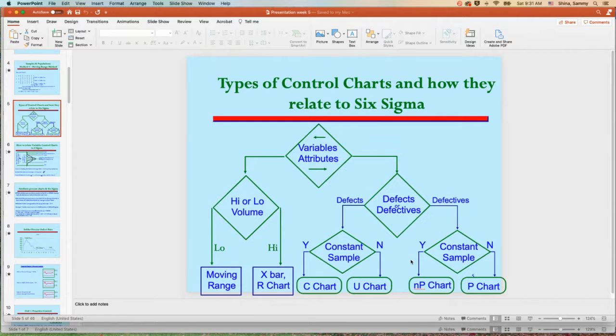So you have a control chart on each spec? Probably not. You have control charts on critical specs. So the question is, how do you relate that to reject rate for the population, which eventually translates to process capability and Six Sigma CPK? So how does that work? That's really the purpose of week 6, and that's why I'm trying to relate that to you.